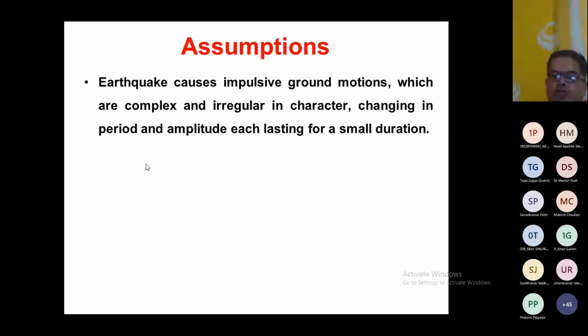So when these low frequency waves reached this filled-up soil, which is soft in nature, and soft soil has the characteristic that it magnifies the earthquake ground motion, this low frequency earthquake was magnified, the frequency was increased, and this frequency matched the frequency of 8 to 15 story buildings.